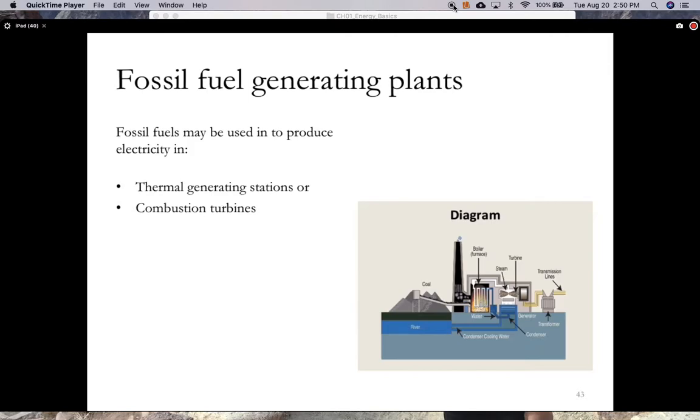And then most of that energy is... so. Here's the steam, and the unused portion of the steam has to be condensed and sent out to the river. A coal power plant is about 33% efficient. So what that means is out of 100 joules of heat released, only 33% is converted to electricity. 67 joules of the heat is dumped into the river. Okay. So out of every $3, $1 is converted to electricity and $2 are thrown out the window.